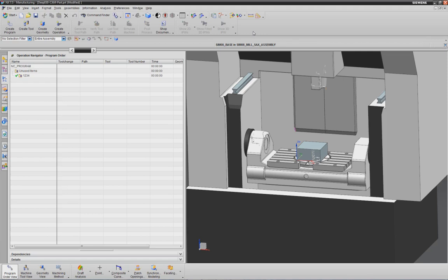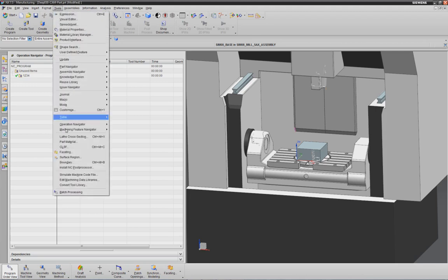In this chapter, we want to look at how CSE actually processes the lines and actually to get our machine moving. At the moment, it does not yet move. In all the training sessions, I will use external file simulation, so with tools, simulate machine code file, since this makes my life easier to create NC programs and to show you the different behavior of the machines.